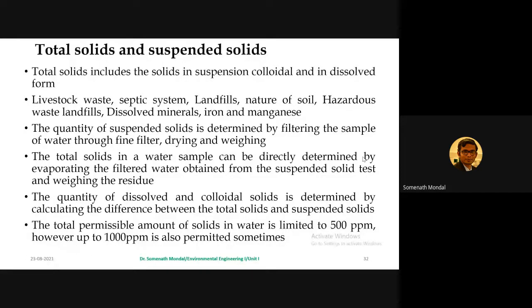Total solids include the solids in suspension, colloidal, and in dissolved form, and the quantity of suspended solids is determined by filtering the sample of water through fine filters, drying, and weighing the samples. The quantity of dissolved and colloidal solids is determined by evaporating the filtered water obtained from the suspended solids test and weighing the residue.